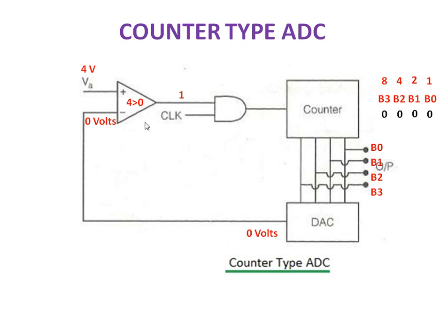At this condition you have to apply clock pulse. If there is no clock pulse, then it is considered as 0. So 1 and 0, according to the AND gate truth table, the output of the AND gate will be 0, so the counter will not be enabled. Now if I apply a single pulse, during this on period the clock will be 1. So 1 and 1, according to the AND gate truth table, the output of the AND gate will be 1.